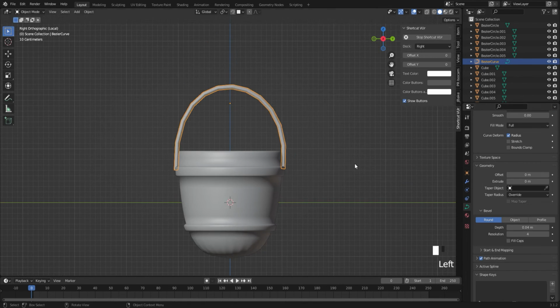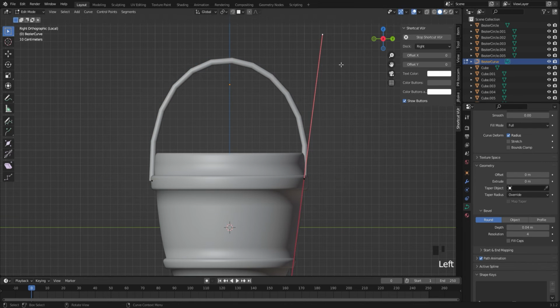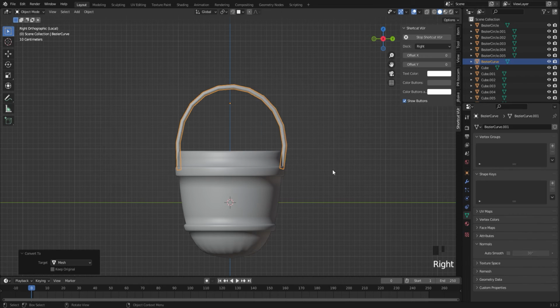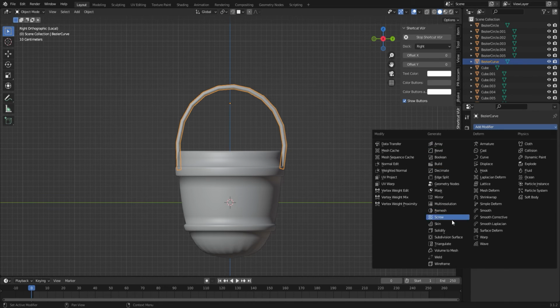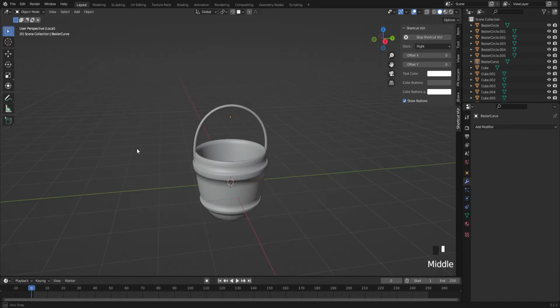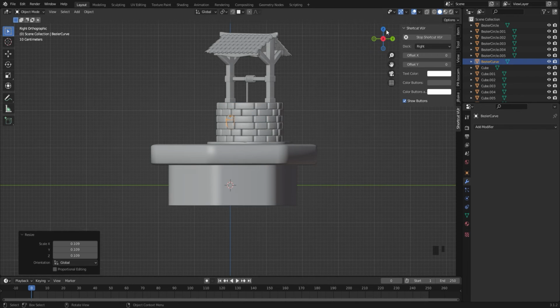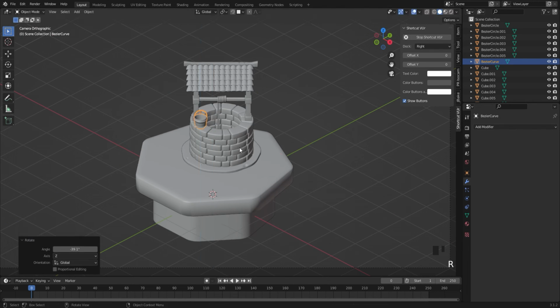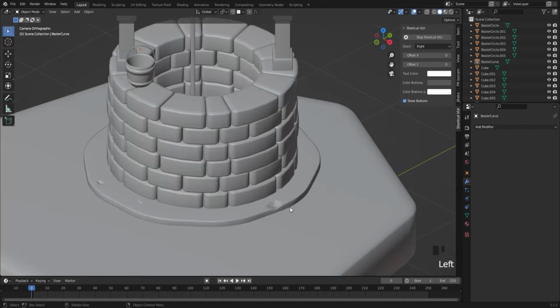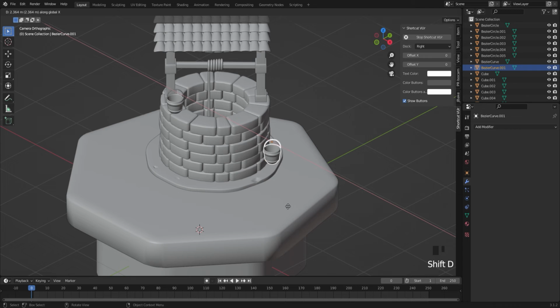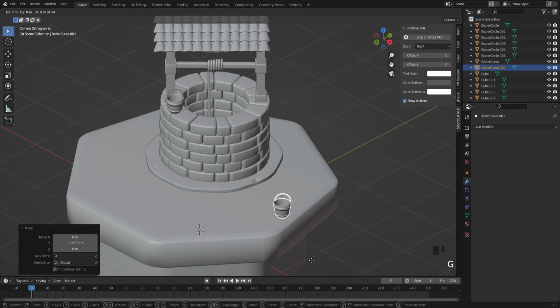Then go to Geometry, Depth and increase it. Shade smooth, right-click, Convert to Mesh and then add a subdivision modifier so it looks better. Then Ctrl J to join both objects, slash to exit isolation view and position it. I'm also making a duplicate and positioning it.